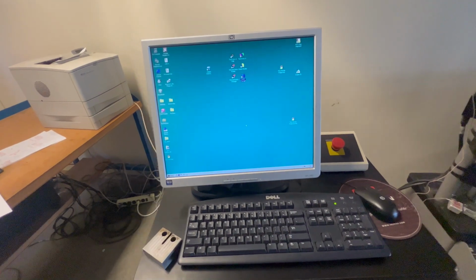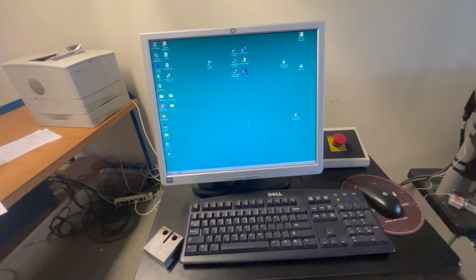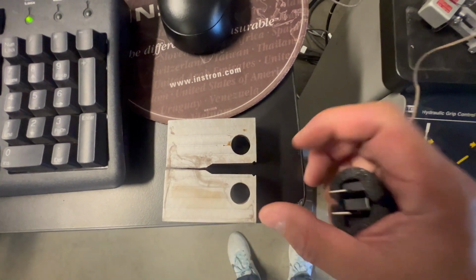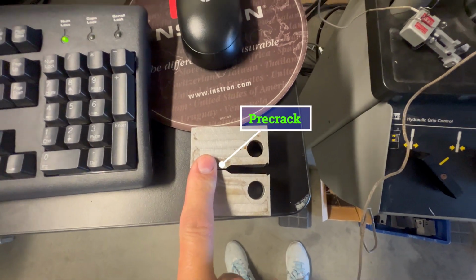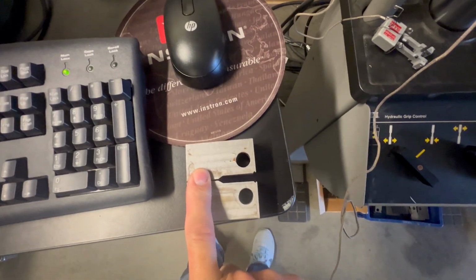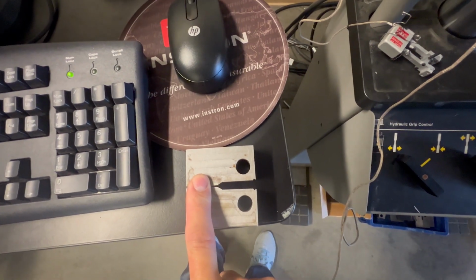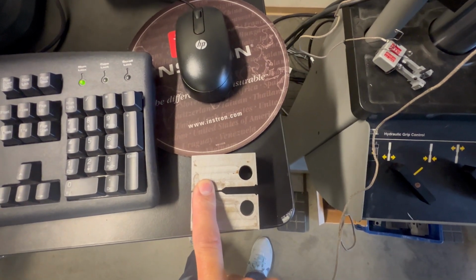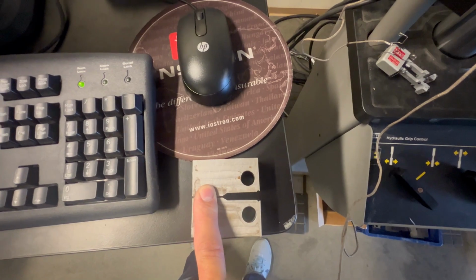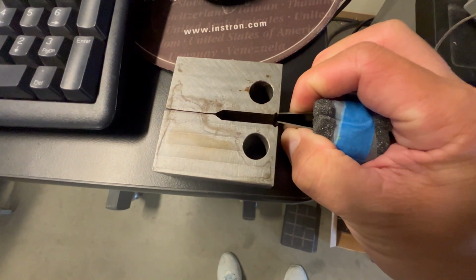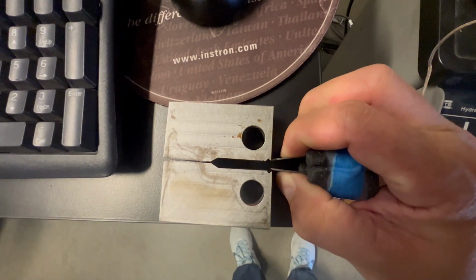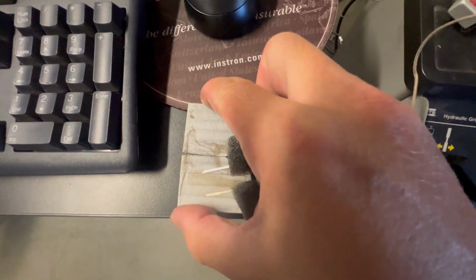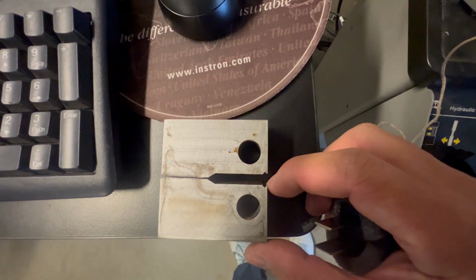Again, following the ASTM E399 standard, to assure the final fracture is all the way through the center of the specimen, other than the V notch, we need to pre-crack the specimen first by applying a cyclic load for a period of time. The peak of this load needs to be over the yield strength of the material. Then the pre-crack is going to initiate and propagate from the tip of the V notch. The COD gauge is mounted at the opening of the notch for detecting the displacement increase of the opening in order to calculate the length of the pre-crack.